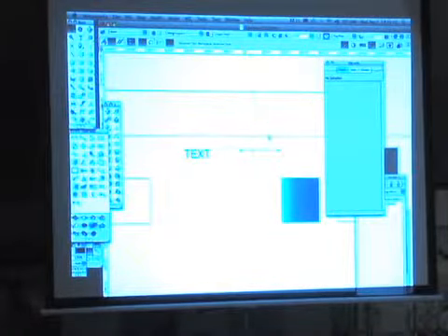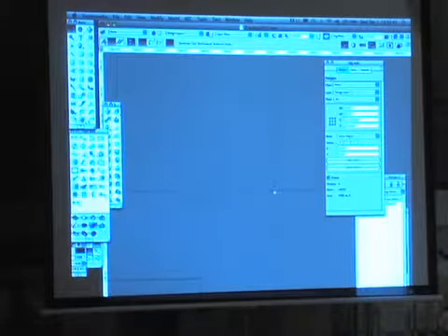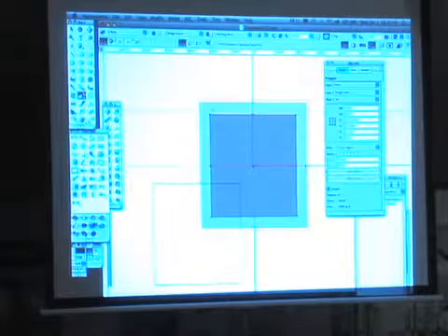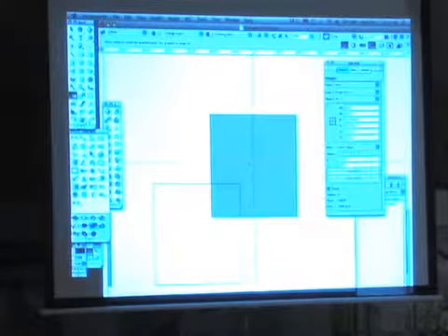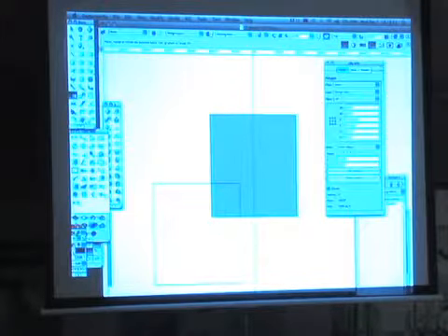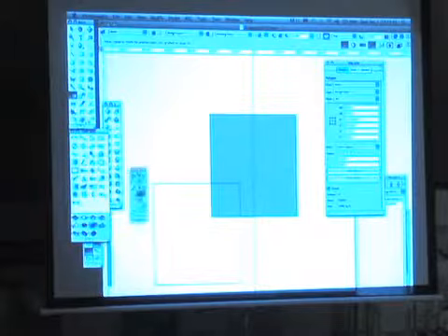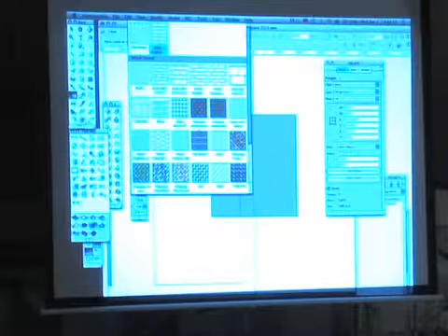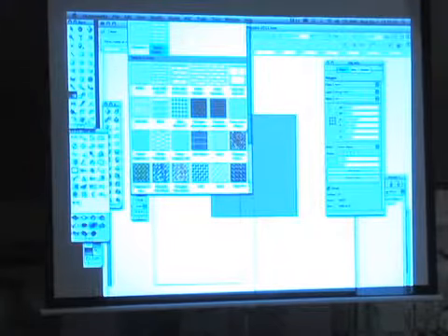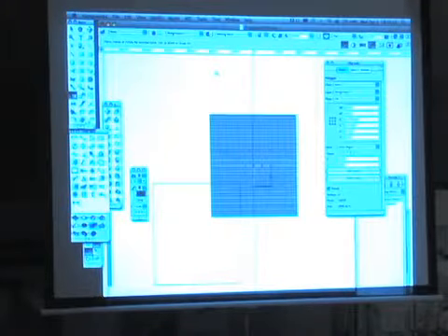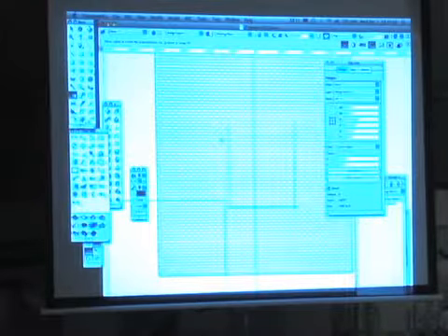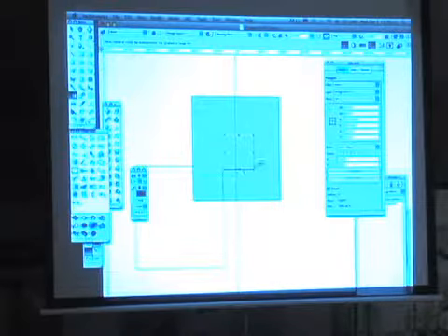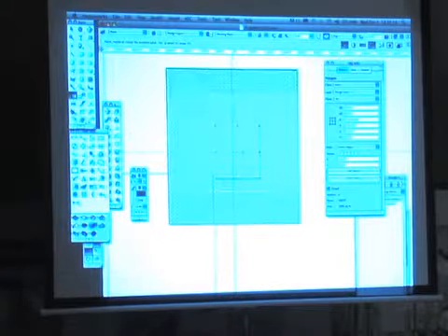So the other thing, I think this became available in, let's see, 8 or 9 as well, is the ability to scale a hatch. Do I have a hatch in there? And also now you get a preview of the hatches. You used to just get a long list of them. So now I can apply a hatch and be able to scale it up and down without having to go in and recreate it.